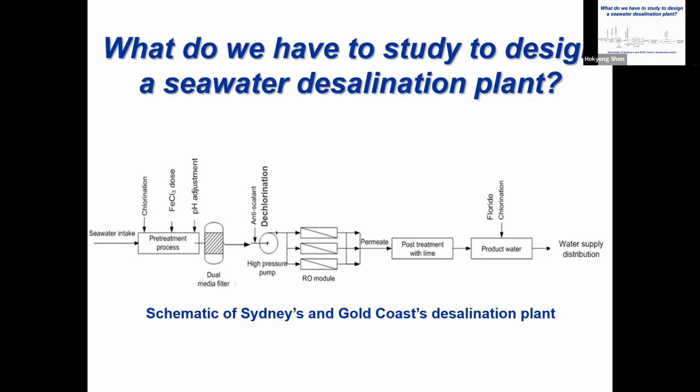So which means the OH alkalinity is a higher concentration inside the seawater. And this will create the scaling. So calcium hydroxide, magnesium hydroxide, iron hydroxide can be easily combined and then create the inorganic scaling.